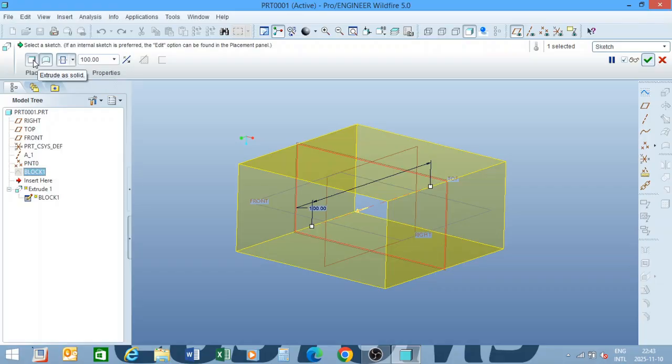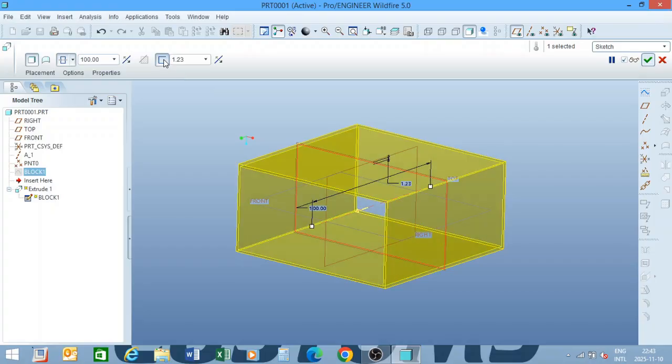So you have to be on the solid function firstly, and then we are going to give it a thickness. Say I am doing a drawing of a 76 by 50 rect tube with a 2mm thickness. I put in 2mm and I hit enter.